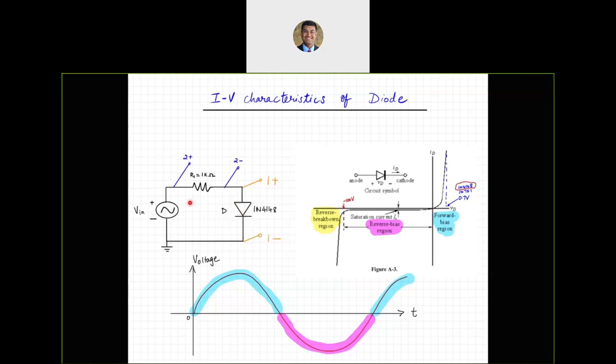But why do we have this R1 in the circuit? Well, the answer to that is the current, I. We need the current information, I sub D. How are we going to find out I sub D experimentally? The way we do that is by using two voltage channels.